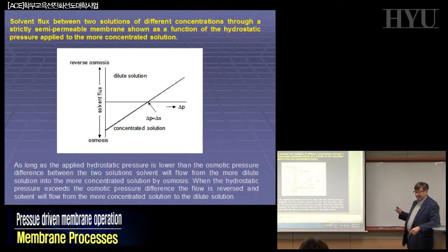Interfacial phenomena can take place in your membrane system because when you extract water, some of the salts that are not going through the membrane will accumulate on the membrane surface, and they are not easily redissolved in the solution. So in all membrane separation you build up what is called a concentration profile in the solution, in the feed. And this concentration profile is at the origin of this kind of problem, concentration polarization. So ideal membranes don't work if you don't use the appropriate driving force.